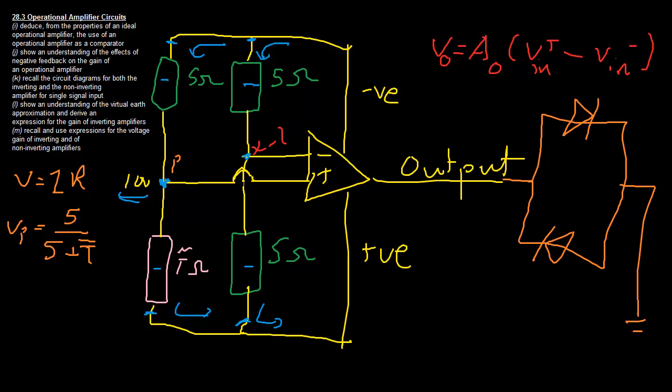So let's take a first case, okay? Let's call this case 1. It's cold, right? So let's say it's 5 degrees Celsius. In this case, the resistance will be high. Let's say the resistance is 10 ohms. So in case 1, the voltage is 5 over 5 plus 10, which is 5 over 15, which gives us 1/3 of the total voltage. Sorry, I should have multiplied this by the voltage, which in this case is 10 volts because it's a 10 volt circuit.